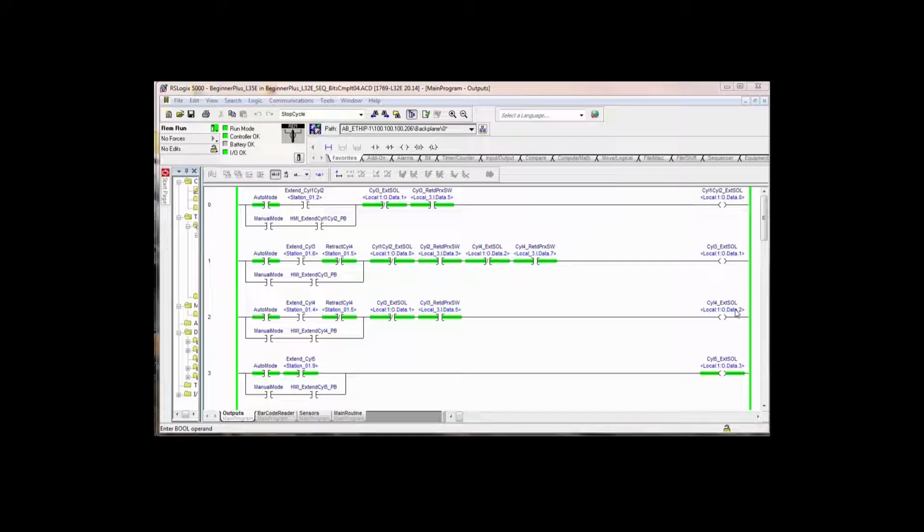So the next step would be to go out to the valve bank, the valve manifold, and if you've got the good solenoid valves, they have a little LED or light on them to show you if they're energized. If the LED on the controller is on, but the LED on the solenoid valve is off, then you've got a problem in between. So then you go get your meter, you throw your meter on that output terminal, and you see there's voltage there. Okay, so the voltage is leaving the controller. Now you've got to go out to the valve and see why it's not turning on the solenoid.